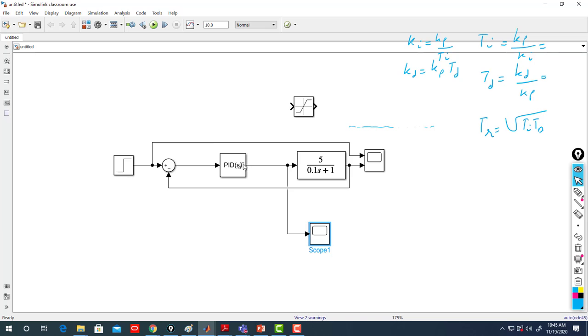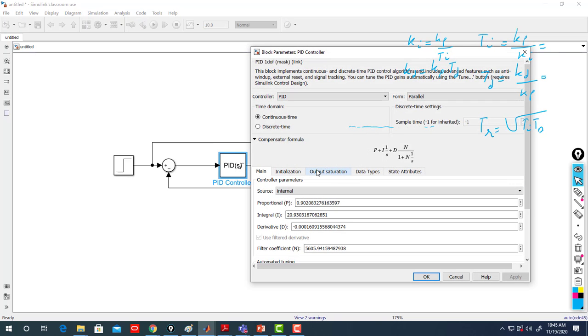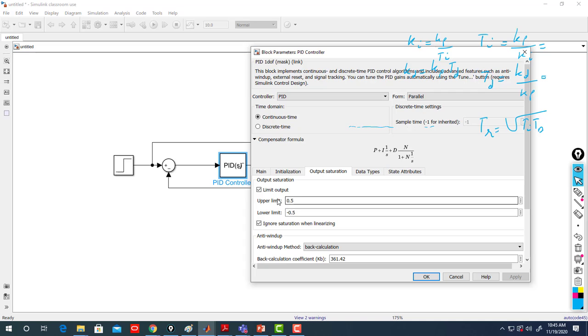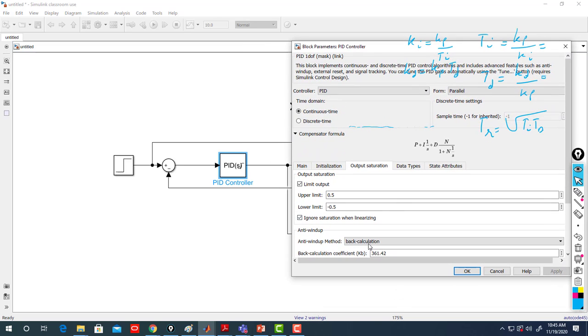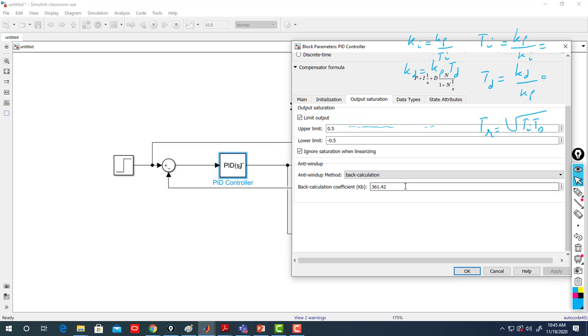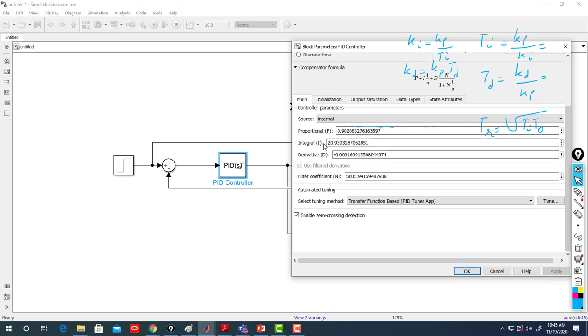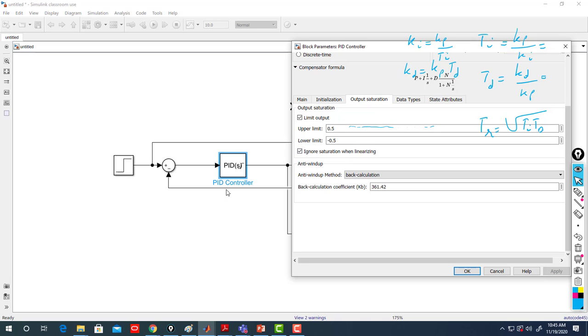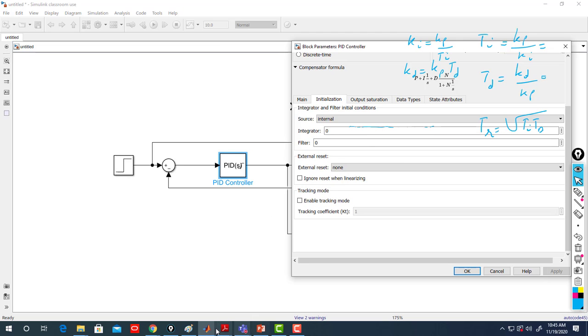So this is basically how to implement anti-windup. You just click here, you put your saturation block as part of your actuator, and once you're done, you need to then tune it yourself. There is no automatic tuning for it. So first you find the PID coefficients, then you tune for it. Also, if you have only PD, you can just find a value that suits you, because you don't have a derivative term for that, so you don't need TD. Any question regarding the anti-windup?